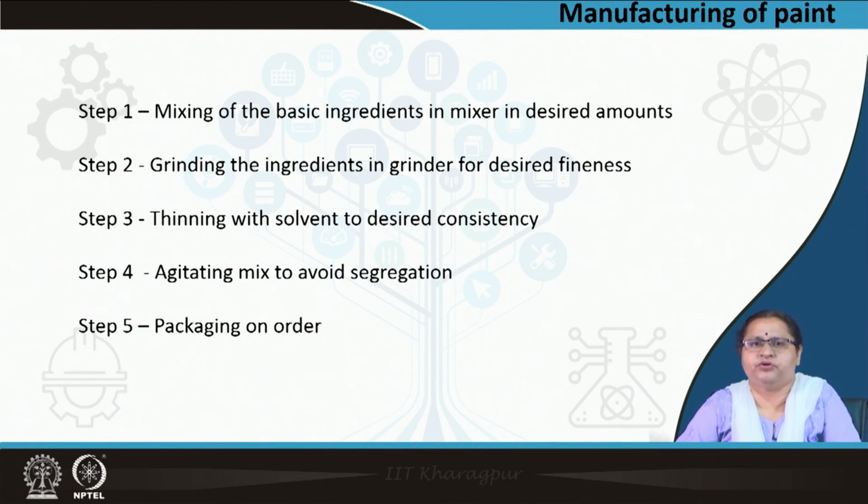Now, you need to keep the entire thing agitated. As you see in the ready mix concrete, you are carrying concrete with the agitation or a vibration so as not to allow segregation. Here also you are agitating not to allow segregation of base from the binder and the thinner, or collectively the vehicle.